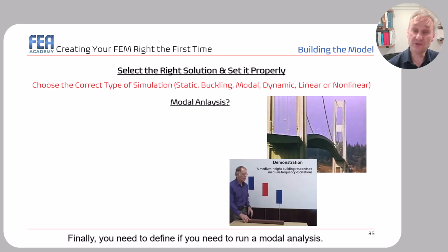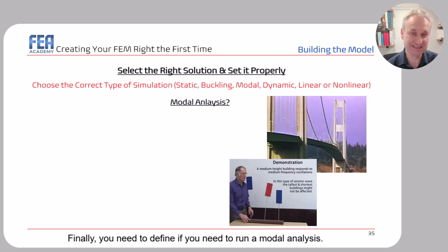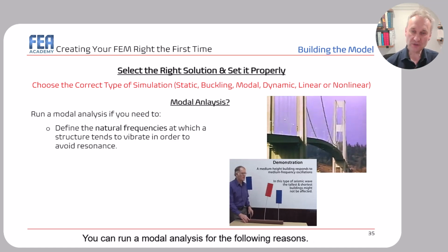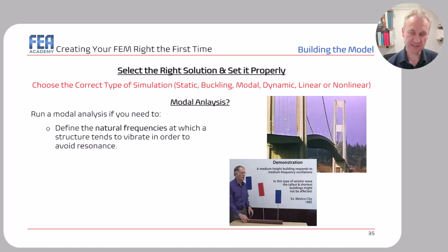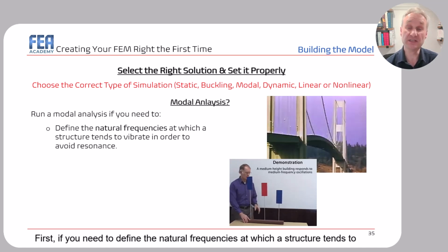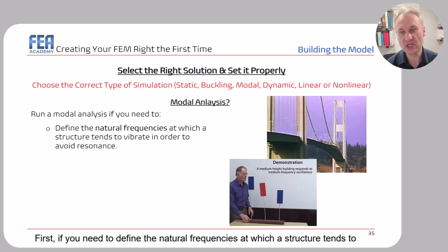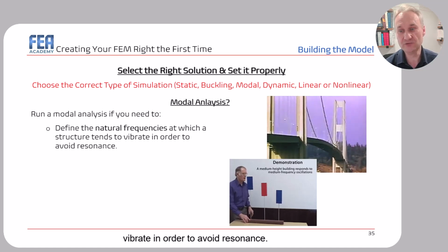Finally, you need to define if you need to run a modal analysis. You can run a modal analysis for the following reasons. First, if you need to define the natural frequencies at which a structure tends to vibrate in order to avoid resonance.